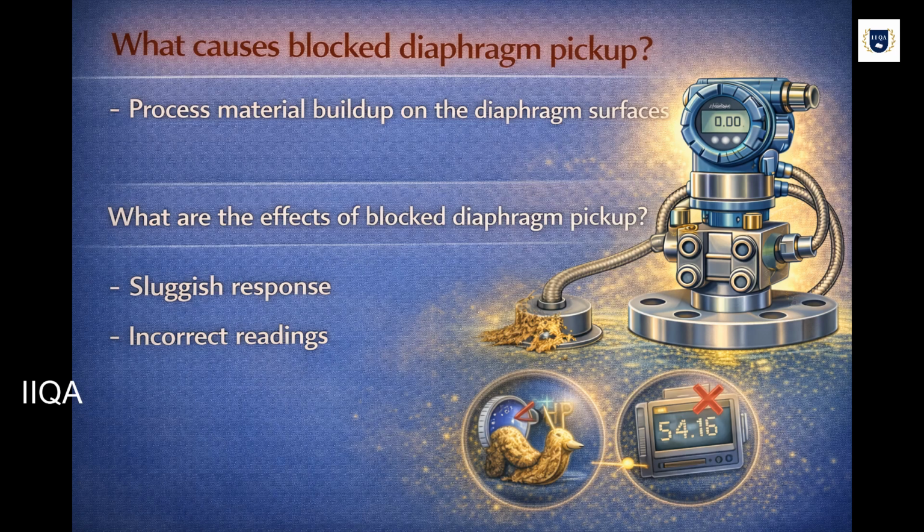What causes blocked diaphragm pickup? Process material buildup on the diaphragm surface. What are the effects of blocked diaphragm pickup? Sluggish response, incorrect readings.